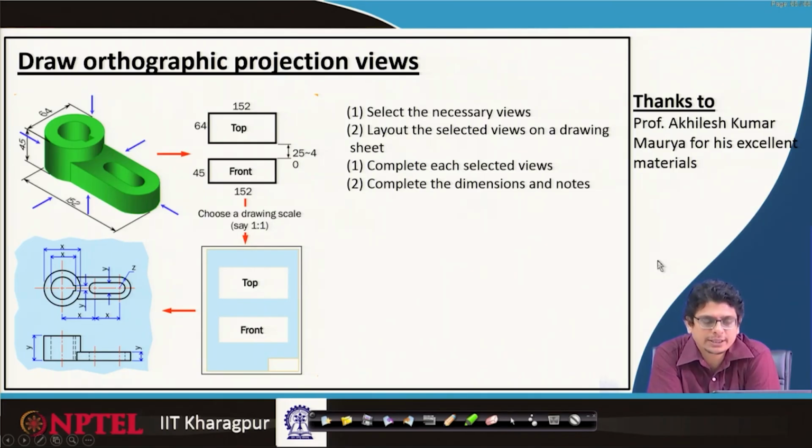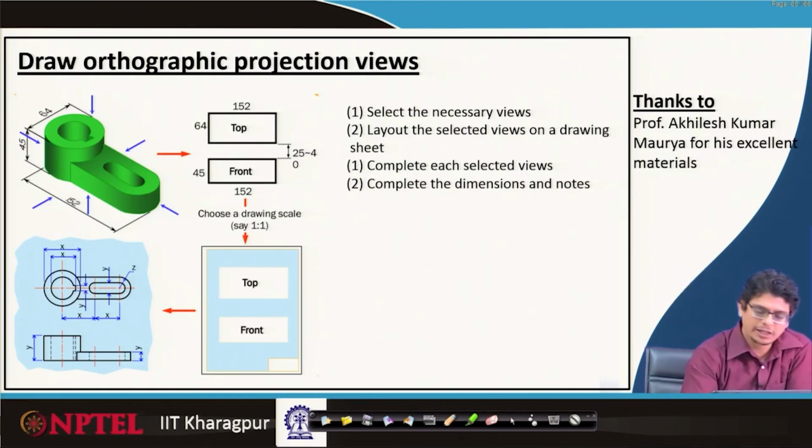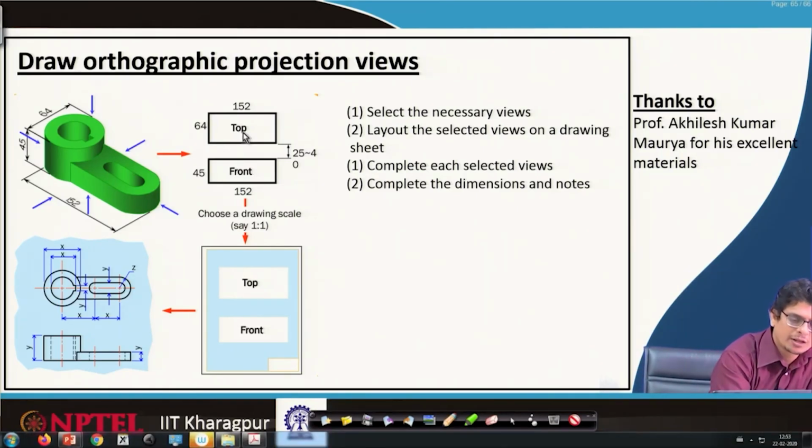Once this layout is chosen, complete each selected view. Begin with the front view, then construct a top view and complete these views. After that, write down the dimensions and whatever the leftover notes. For example, let us look at that.